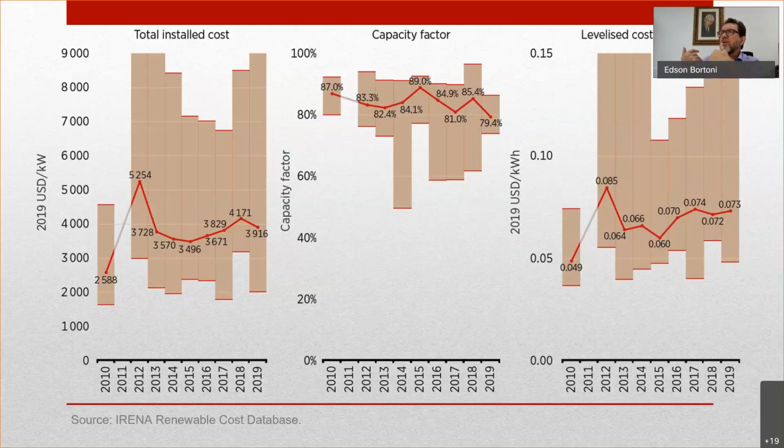It's not because you don't have a power plant, but because you don't have sun. So the capacity factor goes down, maximum 50%. You have 50% of light during the day, 50% of dark during the night. So maximum 50%. But it's much less than that, as we will see.